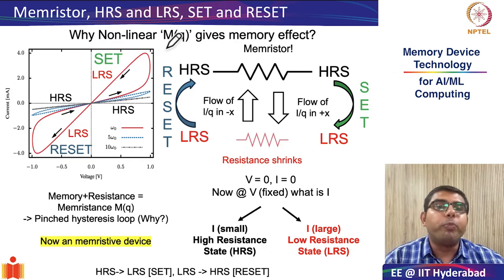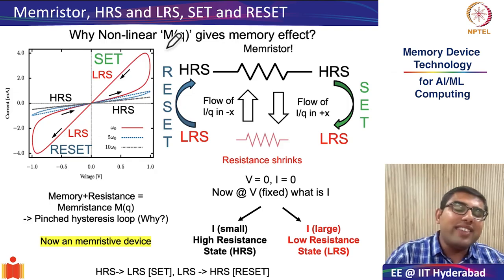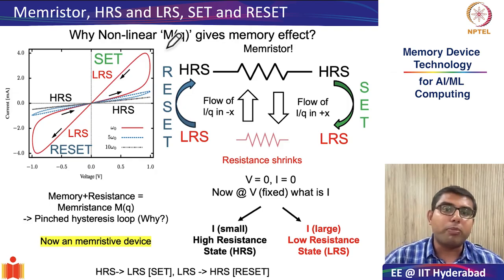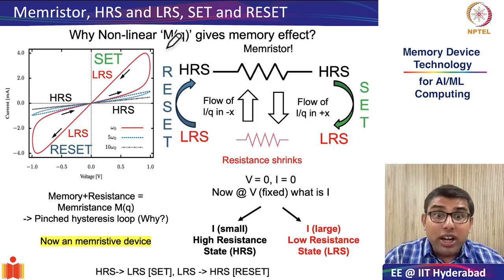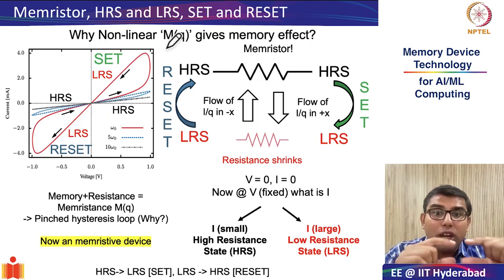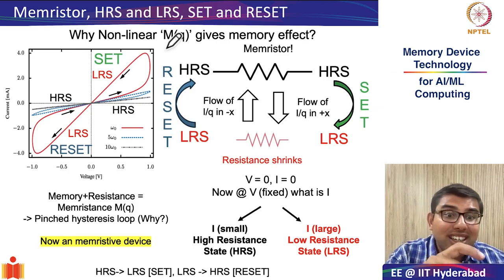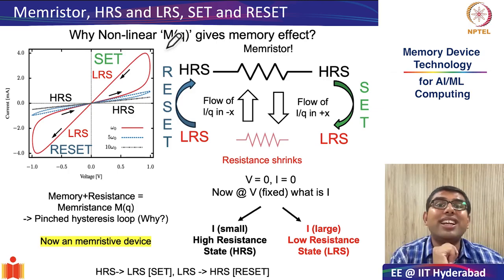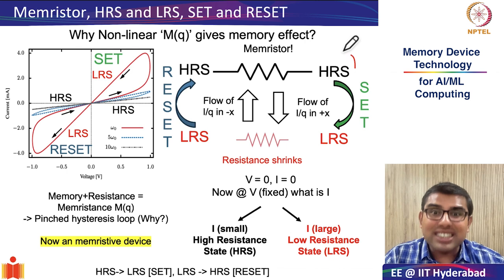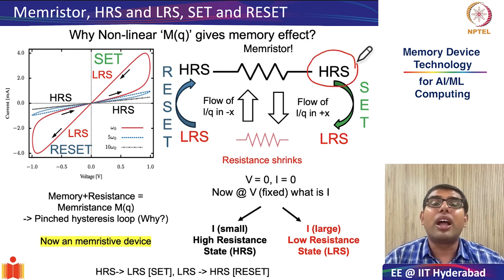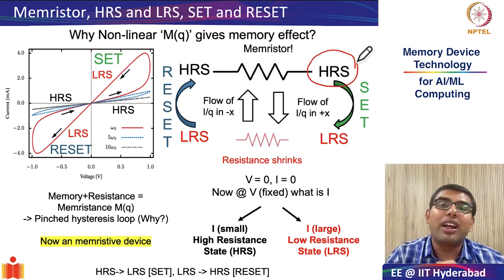It is very simple. Generally, as you even saw in the example of your first memristor from HP Labs, the material between the two platinum metal electrodes was TiO2. Now TiO2 is an insulator. So memristors generally are made out of an active element that is an insulator.